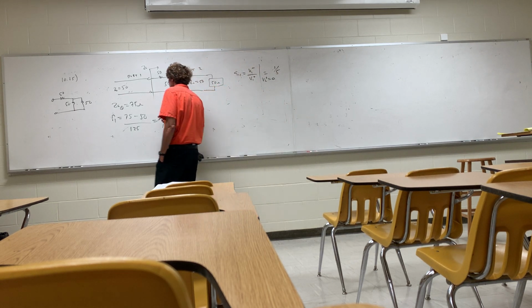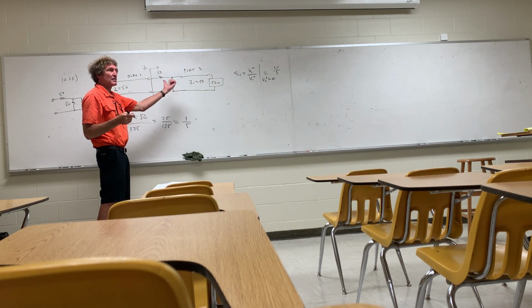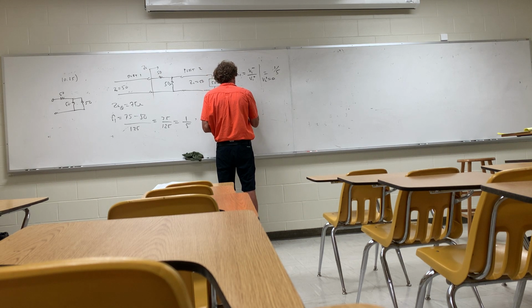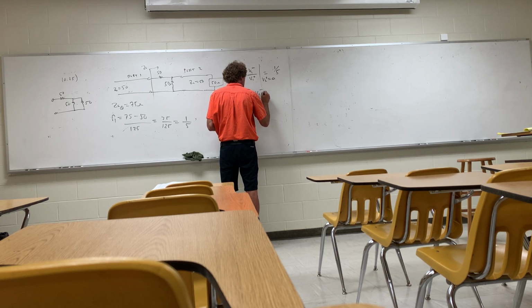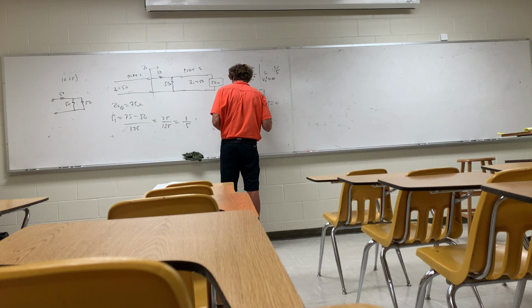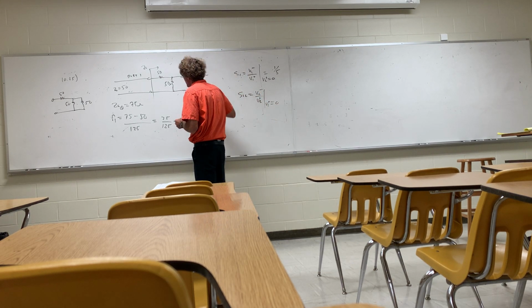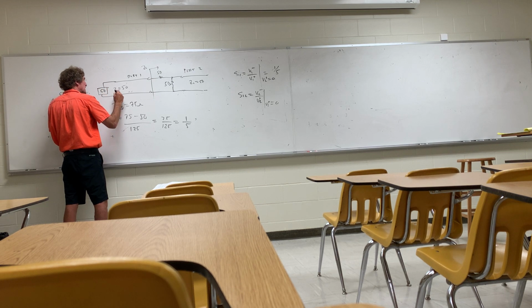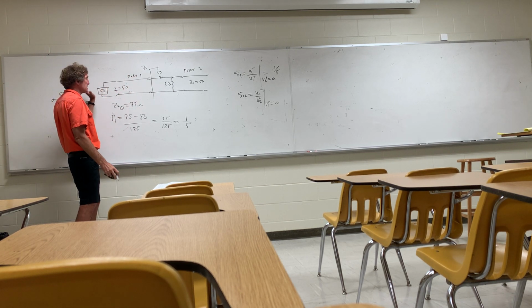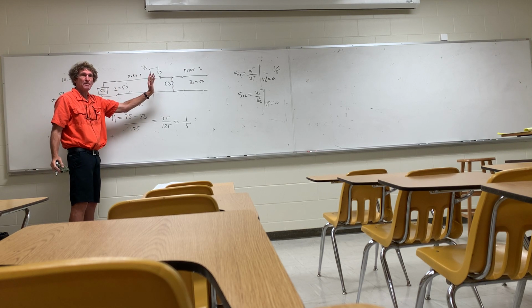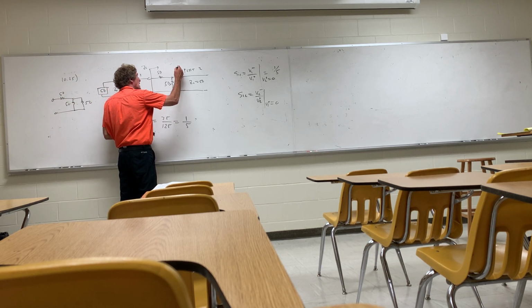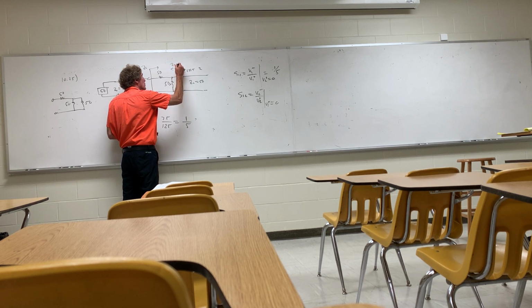All right. Now, take a look back. The next one I'm going to do is S22. I don't have to do this, but I'm going to. So S22 is V2 minus over V2 plus, with V1 plus being 0. So now I get rid of this just for mine. And I do this only because I'm trying to make sure you guys understand. I'm doing this so you know, in your mind, you know there's nothing coming out, hitting something, reflecting back. That'll happen later. But on these, they have to assume match. So here, I want this. So what do I need? I need this right here, don't I? Z in of port 2. You agree with me?